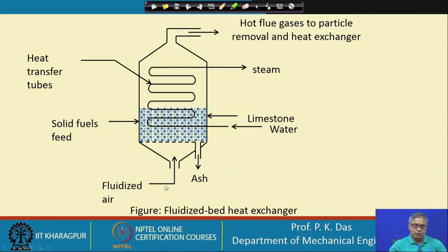Through this one can send air, and with the air this combustible material may be coal dust or some other solid fuel that will burn and produce heat, but that heat will be in this fluidized bed in the solid particulates. When those particulates come in contact with the tube, they will transfer heat. So you see, first the air or the product of combustion is heated, and then that heat, through the granular material, is transferred to the fluid which is passing through the serpentine coil.